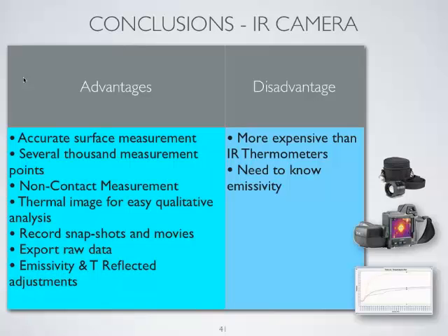And finally, the T420 camera not only has the ability to adjust emissivity, but also the reflected temperature, which is critical in reporting accurate temperature readings. If our goal or objective is to have our apparent temperature be as close to or equal the actual temperature or true temperature of our target, we really need to adjust both of those parameters.